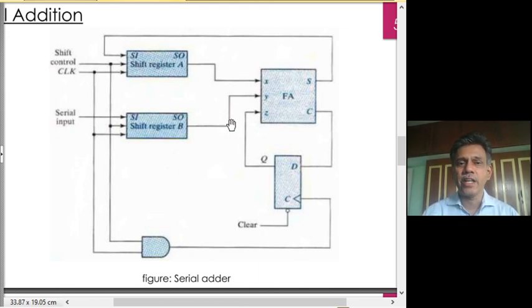And you have to generate a 1's complement number, which is nothing but complementing each bit. So if you put an exclusive OR gate in this path and tie that bit as a 1, then each bit that comes out of the B will be complemented before feeding to Y. Essentially, we will be doing an addition of X with 1's complement of Y with a 1 at the LSB, which is a 2's complement of B being added with A.